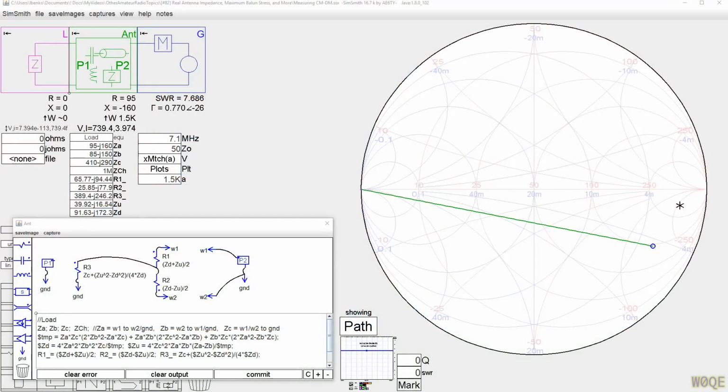I hope everyone realizes that the measured impedance of any real antenna is a function of the distance from the antenna to ground. The typical two-terminal measurement of antenna impedance does not show the effect of ground and predicts a common mode current always equal to zero, which would mean a balun would never be needed. We know that common mode current exists and is measurable, so a better model is needed to allow calculation of balun stresses and the necessary balun choking impedances. This better model may or may not change the results of impedance matching to the antenna.